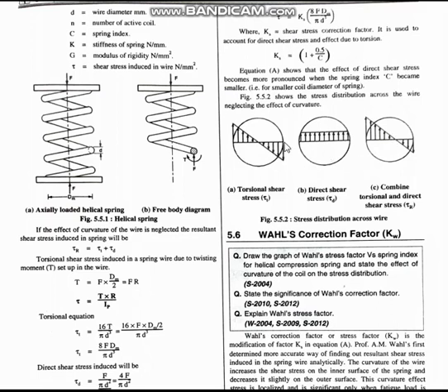Towards this side, one is going down, one is going up, meaning one is positive, one is negative, so the resultant will be less. Whereas on this side both are in the same direction, the positive direction, so the resultant will be more positive. So there will be more shear stress towards this side, less shear stress here, more shear stress there. Because of that, when we are designing, we will be designing at this place.